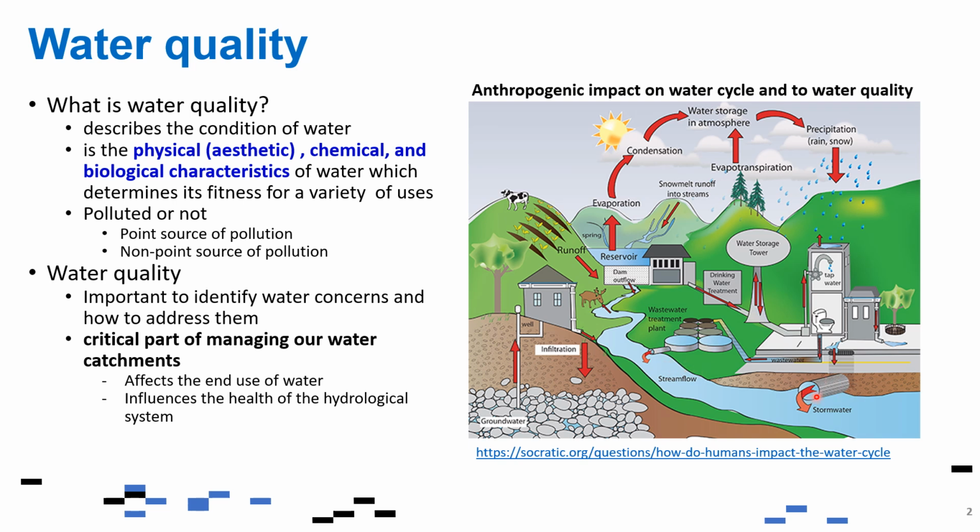On the other hand, there's also a stormwater discharge over here. And you can see other discharges as well coming from agriculture as a runoff. So when you say agriculture, it contains some fertilizers, some nutrients that go to the receiving water. And even some waste coming from animals also goes to the receiving water. So what happens now? The quality of the receiving water will definitely change because of the influx of some masses, some new addition of different contaminants.